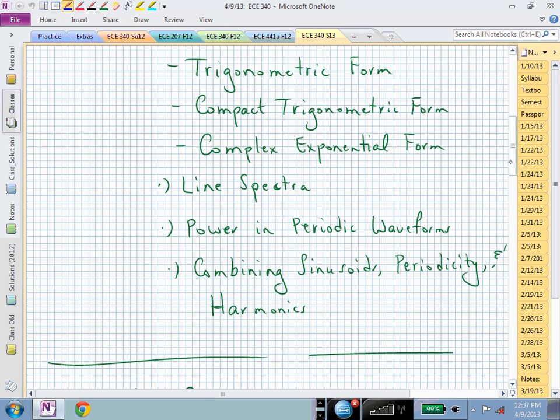And then the power. If I gave you a cosine and said, what's the power in that one frequency component of a cosine, how could you compute the power? If I give you the amplitude, the cosine, omega, and the angle theta, what's the average power of that cosine?